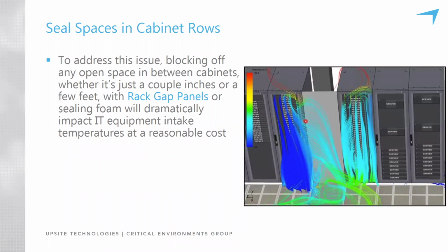And it's important to point out that in both the CFD models for the under rack openings and this in-row opening, there was no change in the amount of conditioned air supplied to the aisle or the temperature of the conditioned air before and after. These before and after images are purely the result of just blocking an opening.